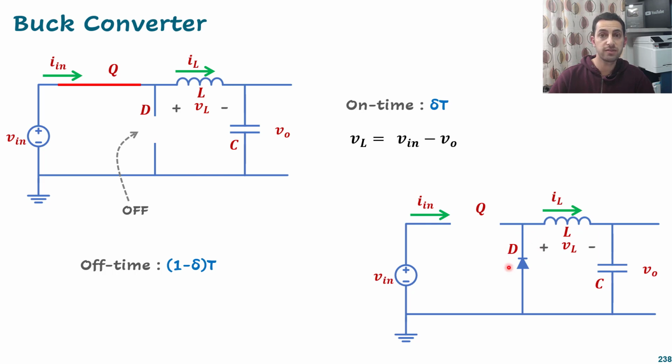And that's why we use this diode here, because without this diode, you are going to prevent that inductor from pushing the current and completing the loop, and this will make the inductor spike and generate high voltage at that node and might damage the switch. So that diode now will work as a freewheeling diode that makes the inductor happy to return the current and makes a complete loop for it, without discontinuing the flow of that current.